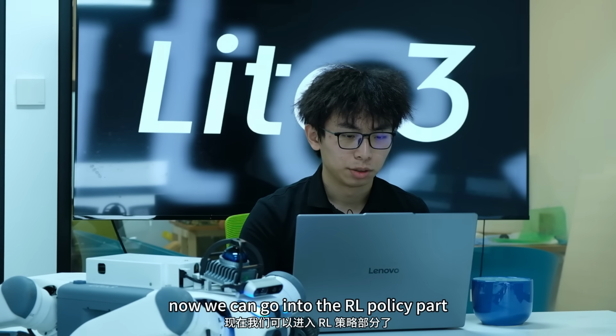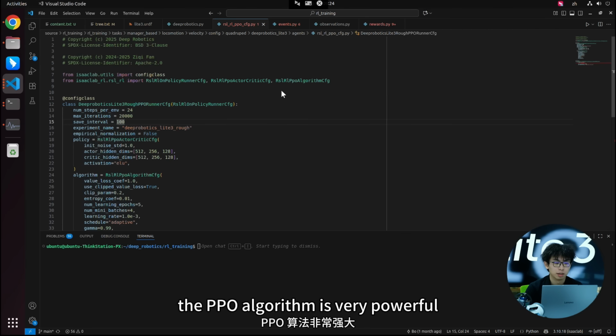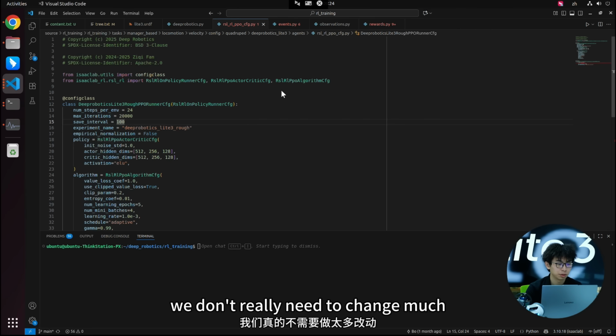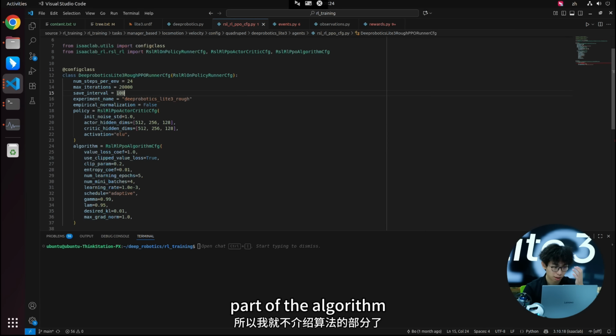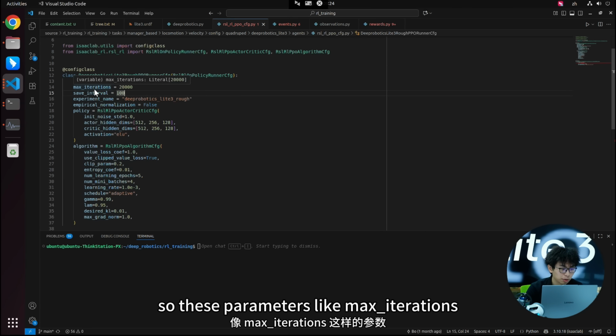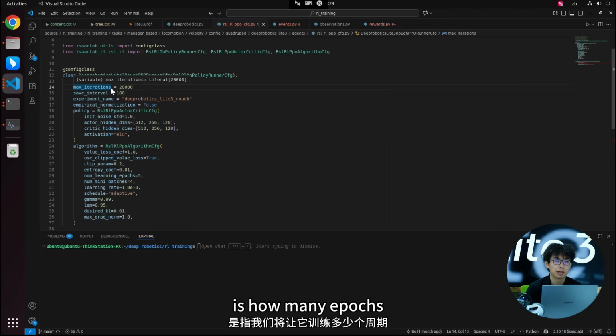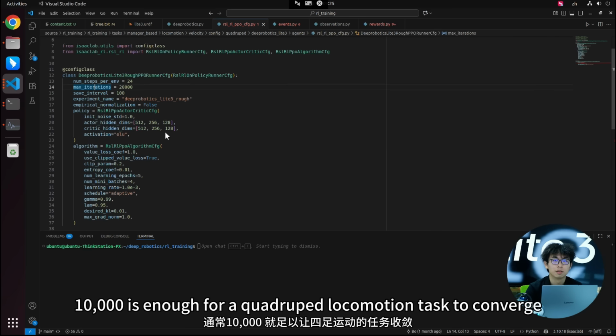Now we can go into the RL policy part. So we are using the very classic PPO RL algorithm here. The PPO algorithm is very powerful. We don't really need to change much. So I'm just going to introduce the parts that we need to change here. These parameters, like max iterations, is how many epochs we're going to let it train. We set it to be 20,000. Usually 10,000 is enough for a quadruped locomotion task to converge.